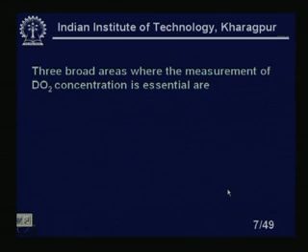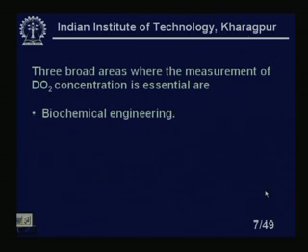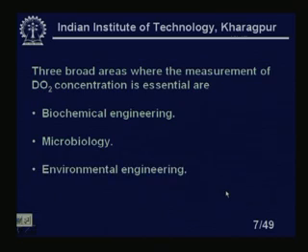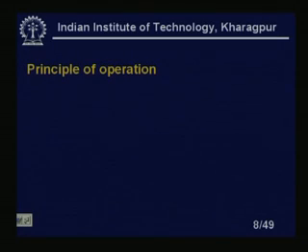Three broad areas, I should say, where the measurement of DO2 concentration is essential are biochemical engineering, then microbiology. Biochemical engineering obviously includes the bioreactor. Then microbiology, and environmental engineering, that means wastewater treatment plants and all these things. There also we need to measure the dissolved oxygen concentration, that is, the partial pressure of oxygen in the wastewater which is getting discharged to the environment.